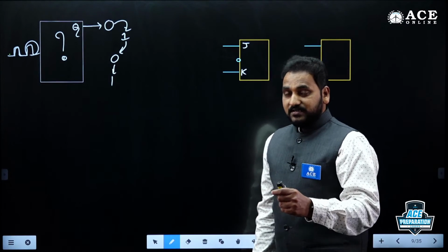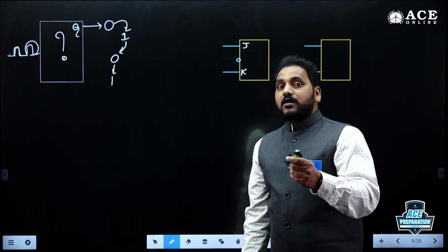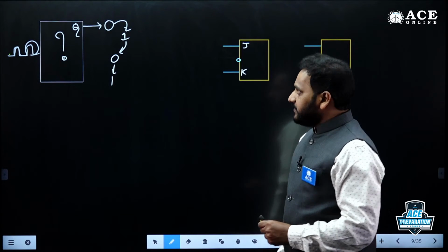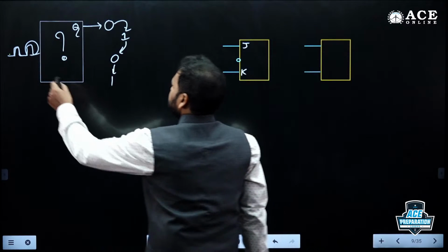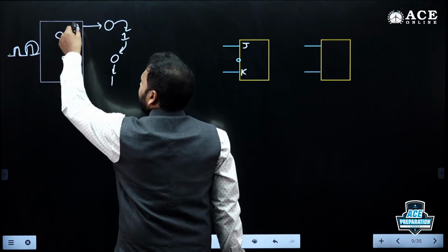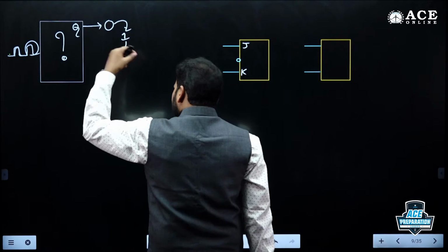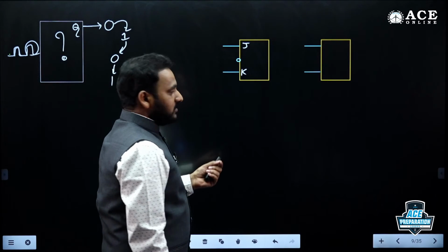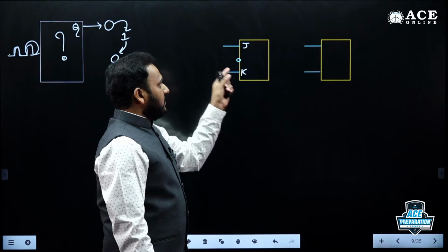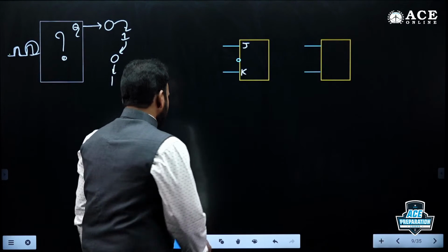Indeed, it is for every clock edge. Alright, we are using the edge triggering type. So just understand, for every clock, the output is going to toggle. Toggle means the complement of its previous state. That kind of flip-flop we are going to use in asynchronous counter design. Okay, coming to the types of clock excitations.